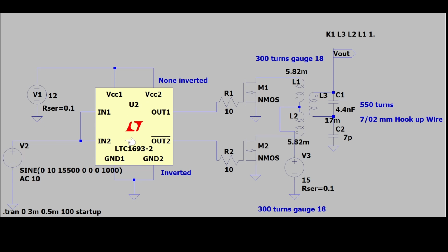So this is a driver. The driver has two output stages. One is non-inverted, one is inverted, and each goes to an individual MOSFET. They do not short. The reason why they do not short when running at the same time is the same as with my zero voltage switching device. Technically that is two class-C amplifiers together getting triggered by the independent wave at the same time. Yes, but no, not at the same time.